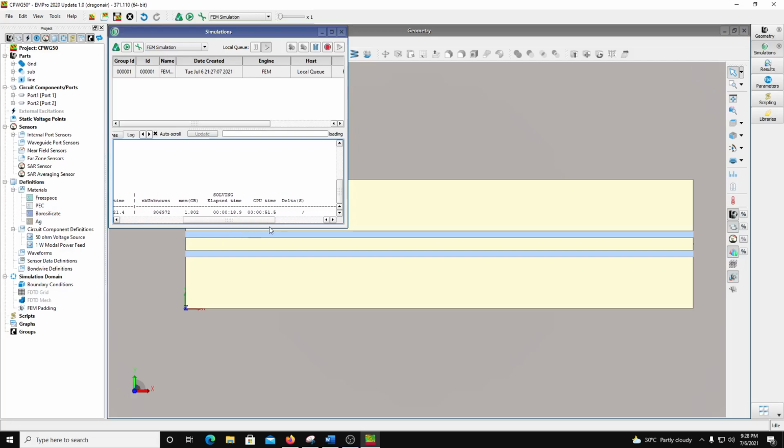And the issue is delta S, so that delta S will come in the second iteration of meshing, which is going to be a finer mesh at 10 gigahertz. So that's coming up. Okay, so now you will know the difference. So that difference is 0.037. It has to go to 0.01. So it will still do a finer mesh.